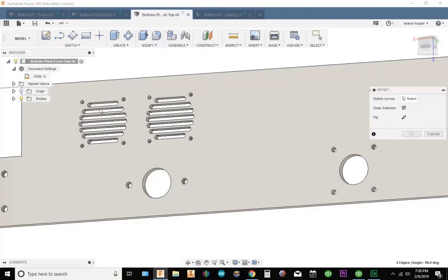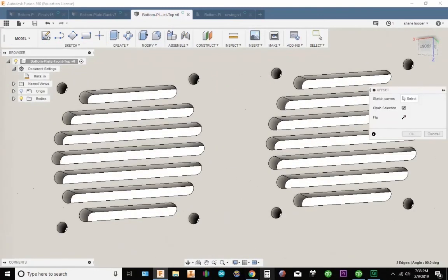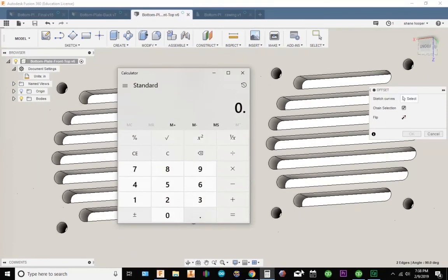and I'm going to go to offset. Now it's 0.118 and I have an 1/8 inch end mill, but I need some kind of room to actually move it around. If I make it exactly an 1/8 inch and use an 1/8 inch end mill, it's going to throw up warnings, and I might have a little trouble getting a toolpath because basically there'll be a little conflict with like lead in and actual step over.